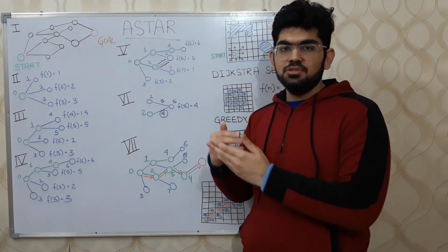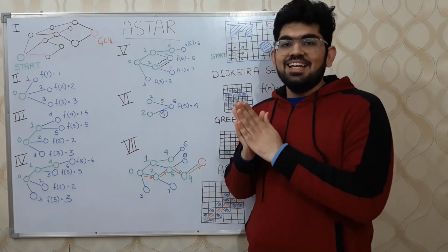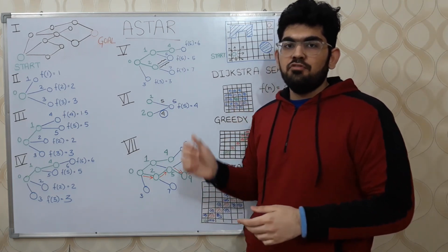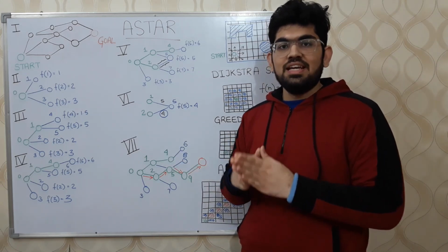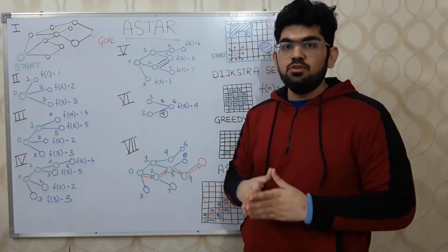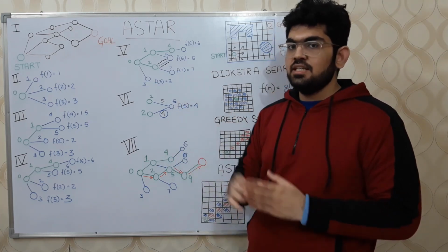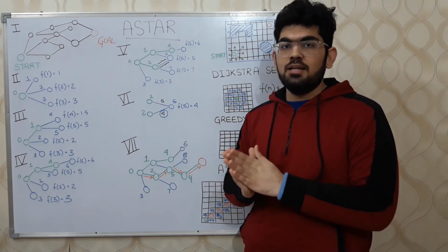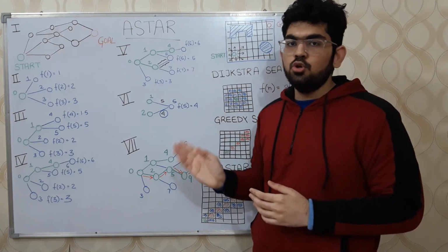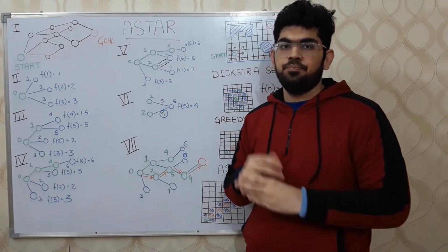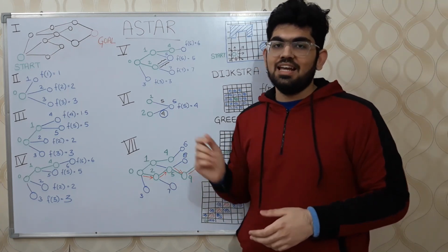However, as we expand through the graph, we see that node 2 is also connected with node 5. Let us consider that the f value of node 5 from 2 is 4. Hence, in order to maintain the shortest expansion, we are going to change the f value of node 5 to the minimum of the two, which is 4. Also, while backtracking, we are going to ensure that node 5 backtracks to node 2 rather than 1. So this is an edge case that we also need to consider while running a path planning algorithm.